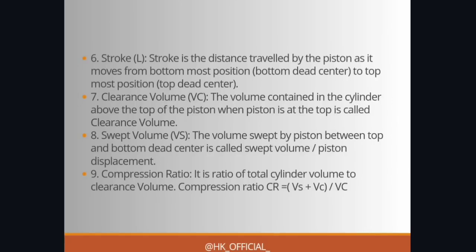Okay, so the distance which the piston travels is nothing but your stroke. Then clearance volume is there. I have explained you. See, the volume contained in the cylinder above the top of piston when piston is at the top, that is called your clearance volume. Then swept volume is there. The volume swept by the piston between TDC and BDC.